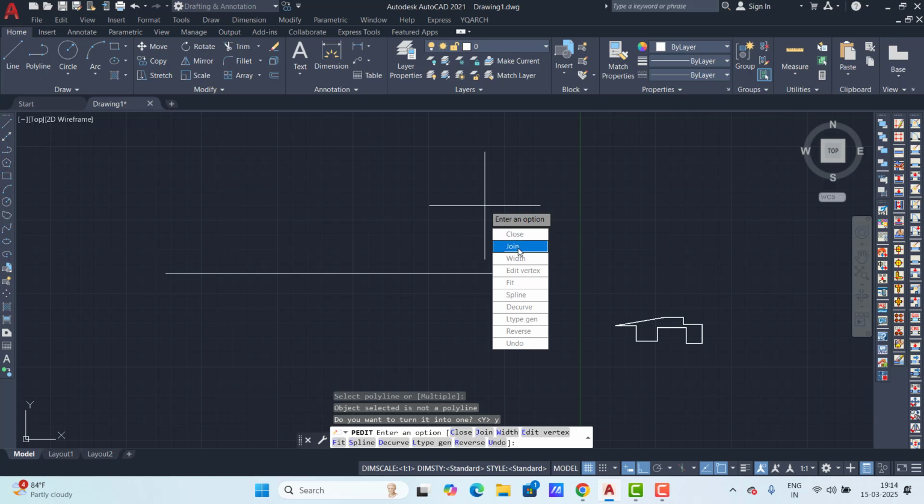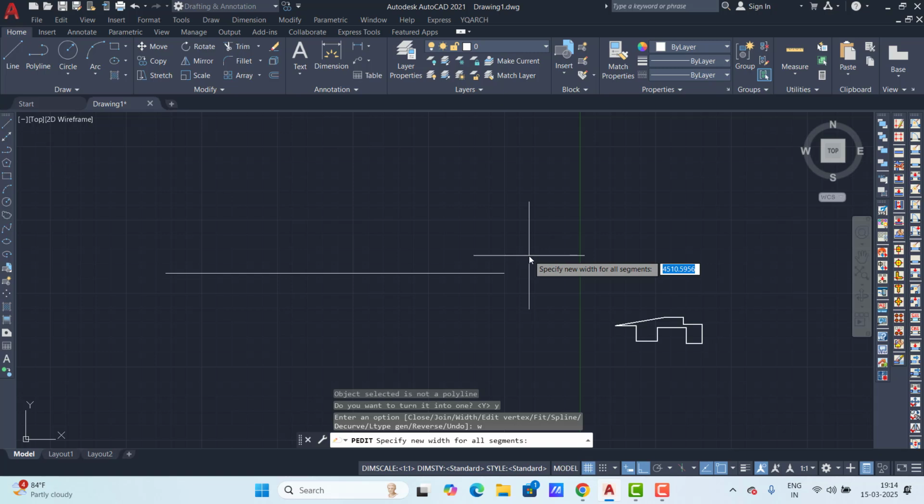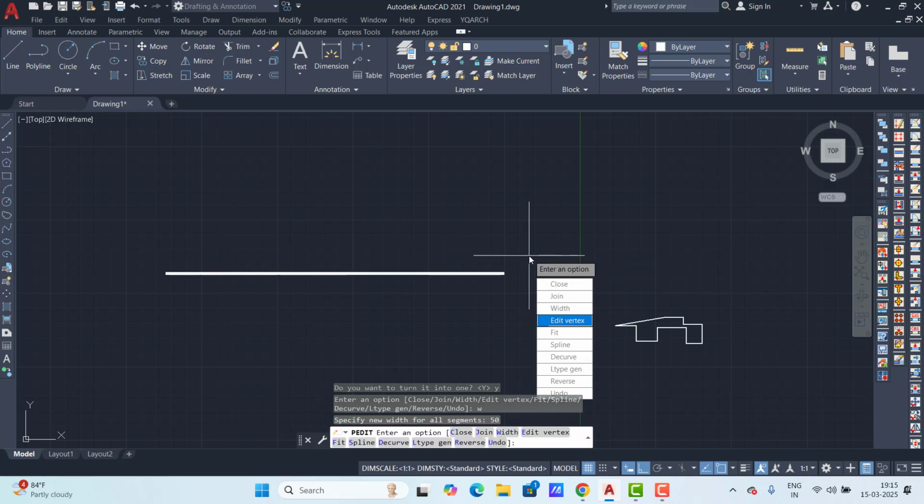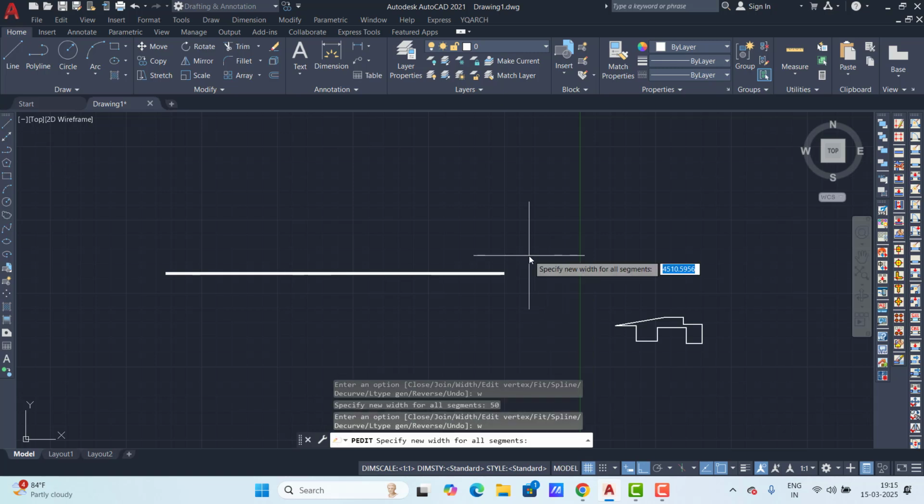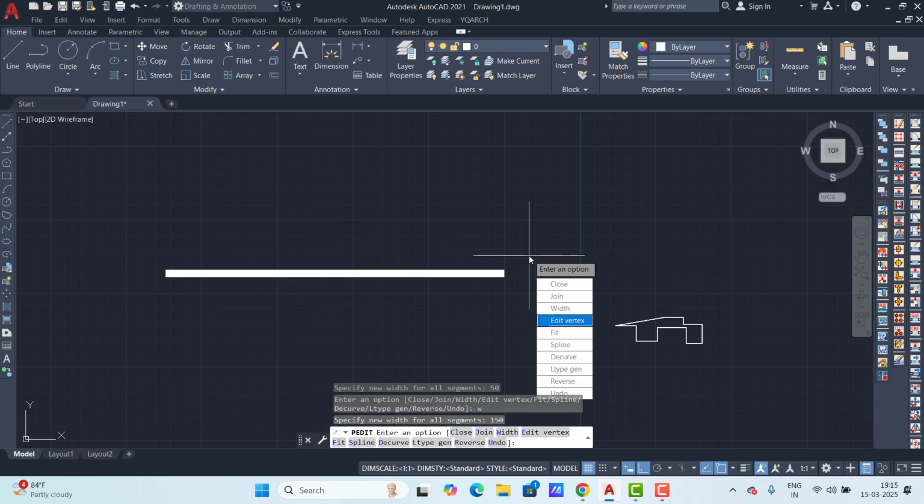Once the polyline is converted, you can see the property thickness, global width, coming. So with this one selected we can change the width option here. Again selected, we can change the new width. So this is a polyline. Again, we can convert it to an arc. Now, more properties for understanding polylines.